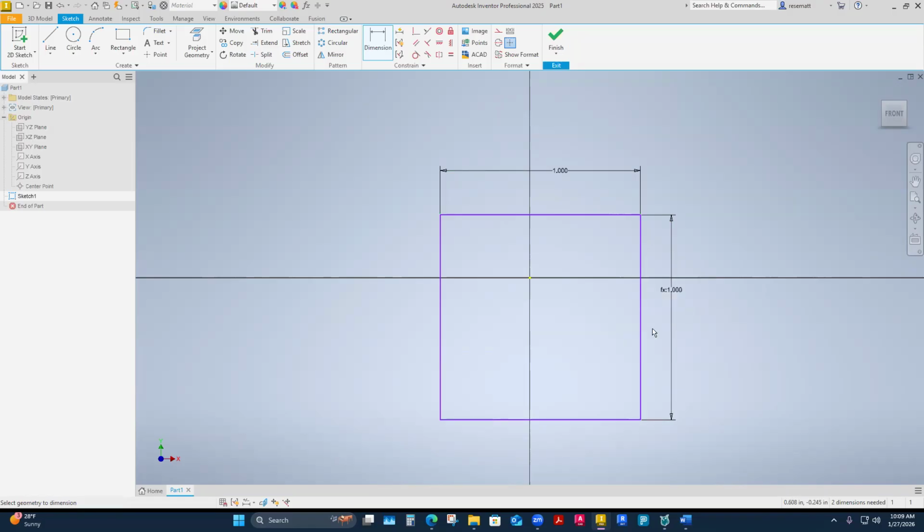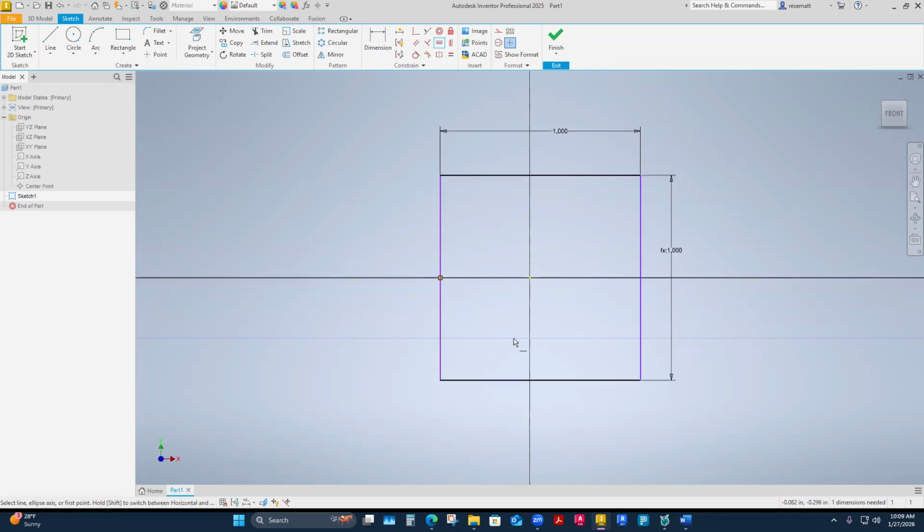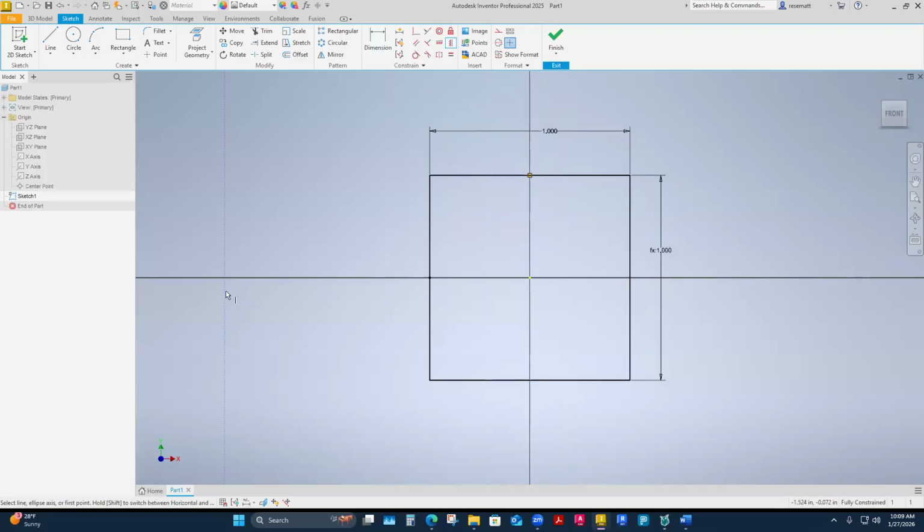I'm going to constrain it over the midpoint with no dimensions. I'm just going to use geometric constraints. So I'll do a horizontal constraint to the midpoint of one of these sides, either side really. I'm going to do the midpoint to the center point here. That's going to push it up there. Those two are going to always stay in alignment. I'm going to do a vertical constraint from the midpoint of either side to the center point, and that's going to constrain my geometry. I only have one piece of data to ever change in there. That dimension is the only thing that I can change.